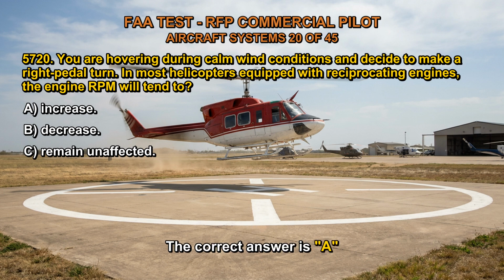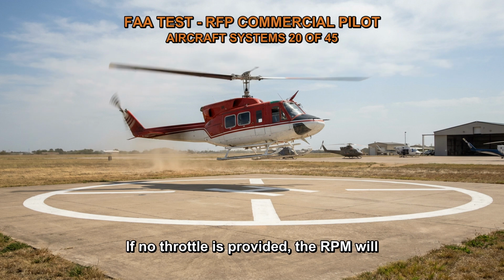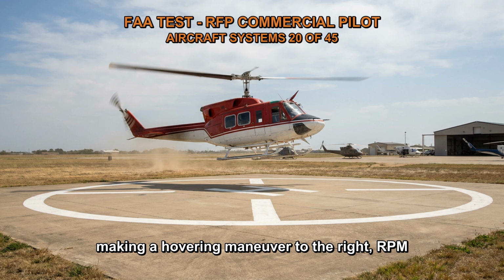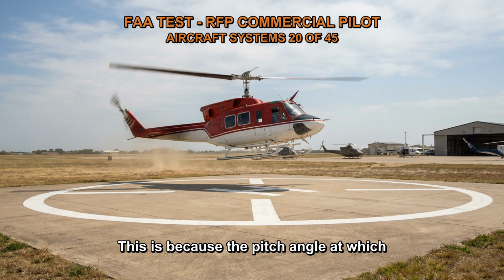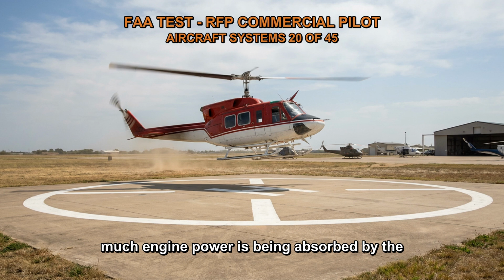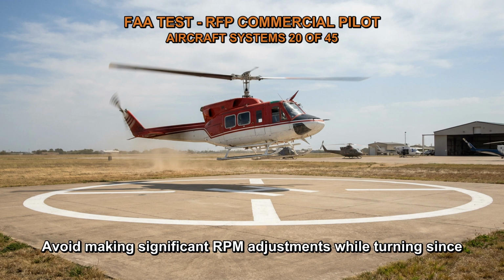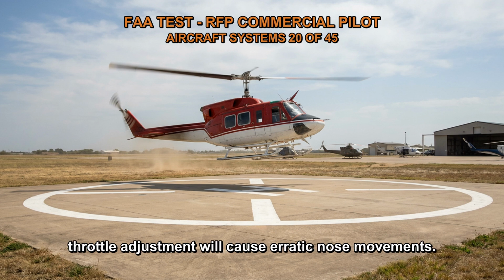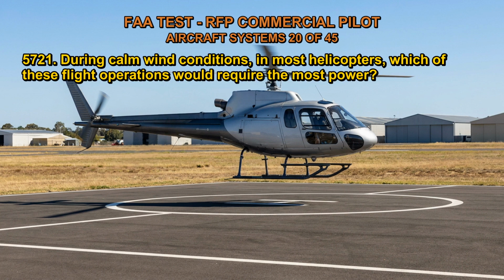The correct answer is A. If no throttle is provided, the RPM will fall during a hovering left turn. If the throttle is not slightly reduced when making a hovering maneuver to the right, RPM will rise. This is because the pitch angle at which the tail rotor blades are operating determines how much engine power is being absorbed by the tail rotor. Avoid making significant RPM adjustments while turning, since the fluctuations in torque brought on by the throttle adjustment will cause erratic nose movements.